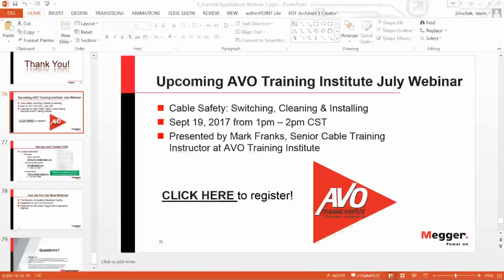The termination normally is exposed to the outdoor environment, right? So it sees a lot of aging that the cable itself underground doesn't see. It has the UV issue and all these things. So it's a good thing to look at that first, because it's fairly inexpensive to do that compared to putting a new circuit in, and that has been proven by quite a number of utilities.